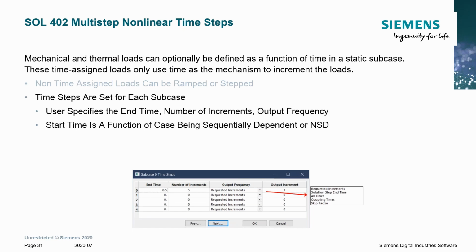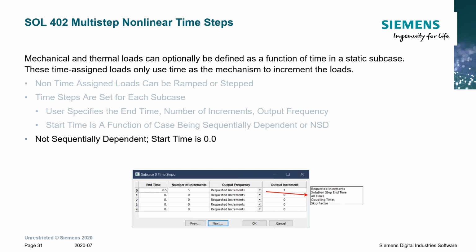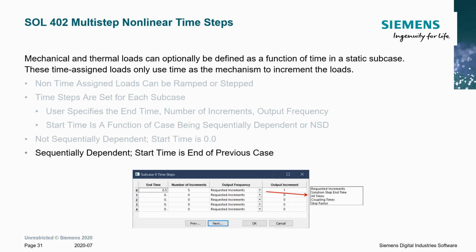And then just like in 401 or advanced nonlinear, you specify an end time, number of increments, and the output frequencies. And again, start time is based on being sequentially or non-sequentially dependent. Again, for non-sequentially dependent, start time is always at 0.